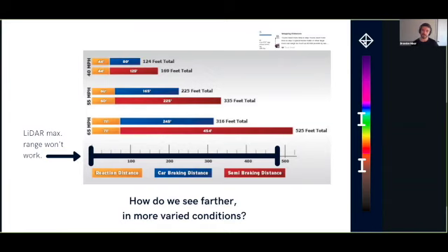However, the LiDAR max range for most LiDAR, even very powerful LiDAR, is less. You can get about 490 feet or so at the most powerful, and even then there's some uncertainty in your measurements. So if you're relying on a LiDAR module to tell you when to stop for a heavy truck, you're going to run into something.